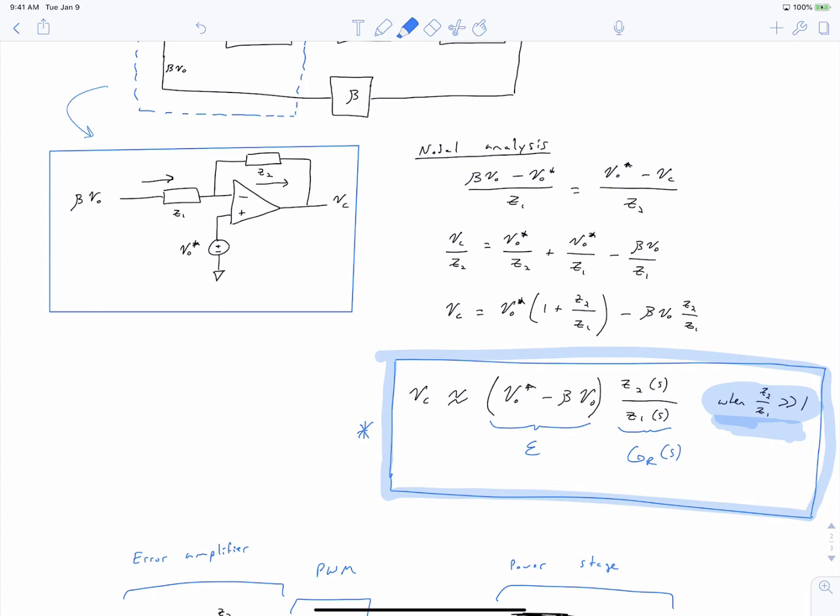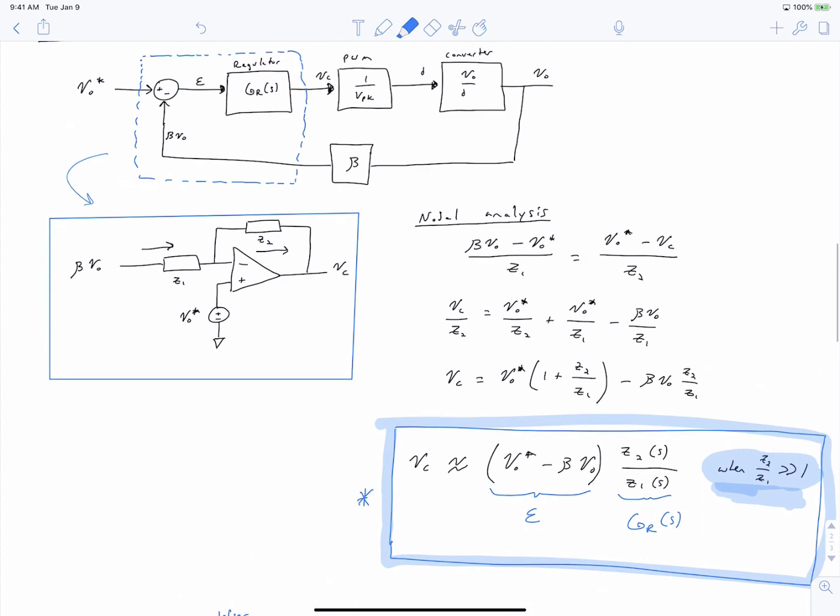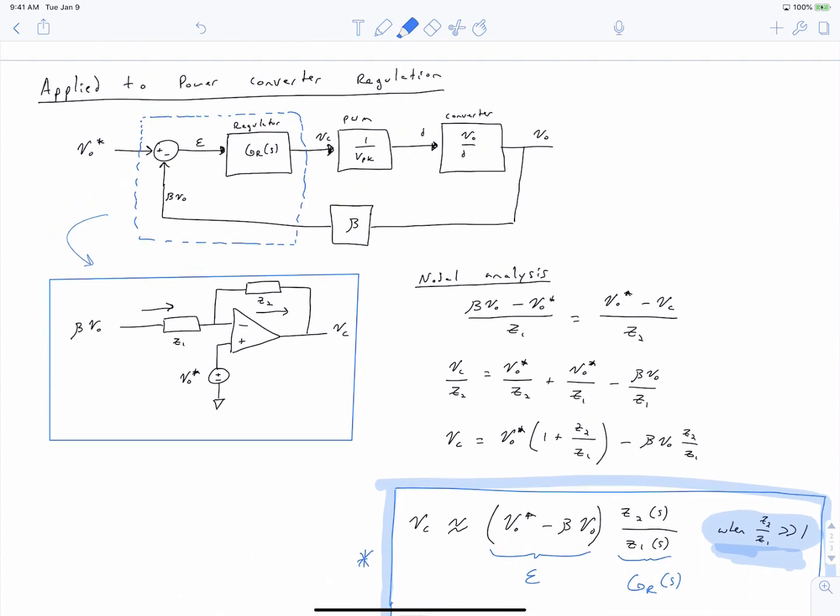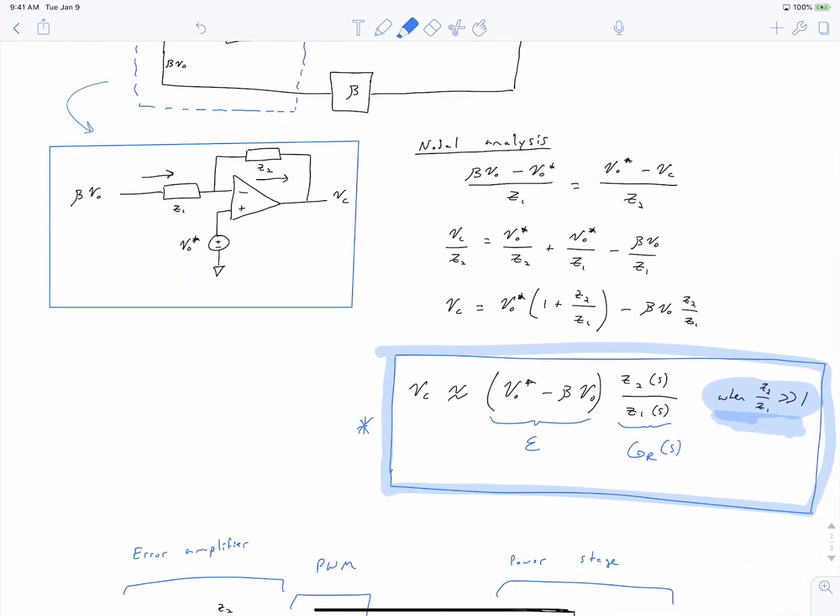There are other op-amp circuits, for example difference amplifiers, that would not require this but would have more elaborate feedback networks. This simple circuit, you can in fact go buy a part for this which will implement the op-amp alongside a reference voltage all within one IC. In fact, you can find parts that will also add the PWM stage to this as well. So this is a common approach to make this kind of simple circuit work for your regulator design, because as long as you satisfy this criteria, it's a very reasonable and accurate system.